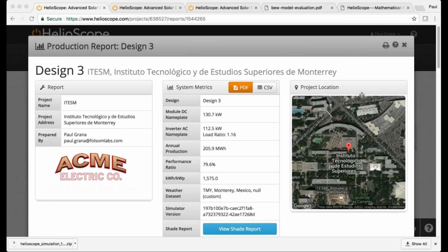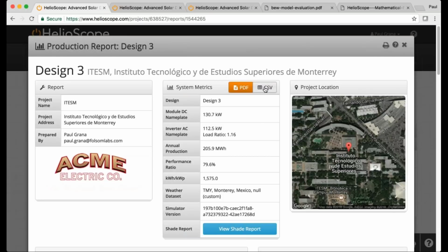And then the final thing is grid power here. So this column is typically the most important number because this is what you're actually getting. How much energy are we getting every hour for every hour of the year? So again, that's what HelioScope is generating every time you run a simulation. And that's the primary thing that's exported to Homer. But just wanted to point out that behind those numbers, A, you can always download them yourself if you want, and B, behind that is a detailed weather file and module level calculations for the array. So that's basically the